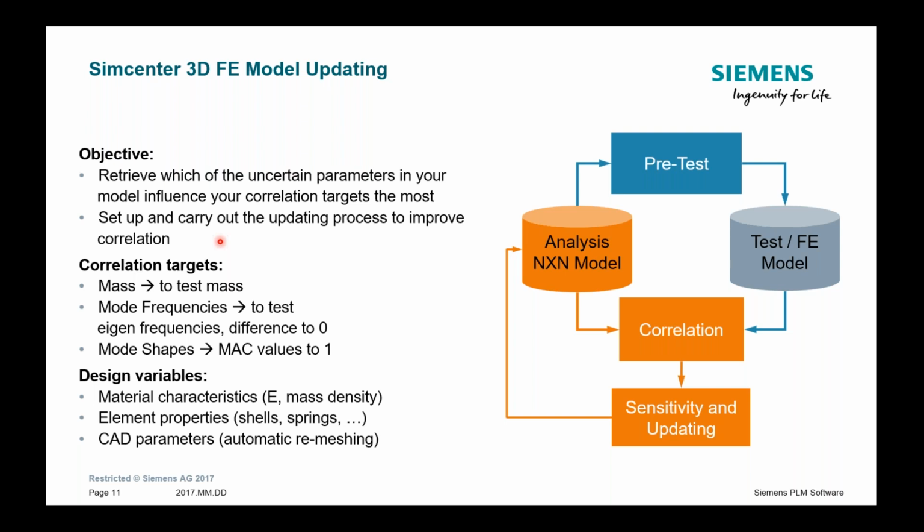As an analyst, you might not be too confident in how that has been modeled. So you want to take that information and, depending on the different components of the model, do some sensitivity studies, like how sensitive a group of elements are, or take some design variables like the Young's modulus and mass density element properties, and characterize how confident you might be in those.